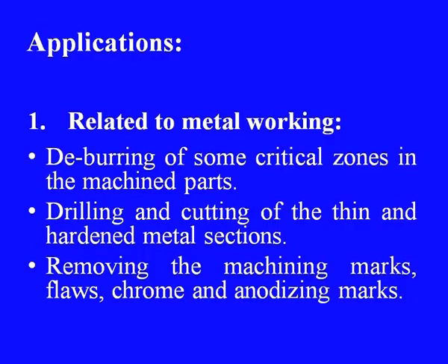Now, let us look at the probable applications of this particular process. These applications we can group under a few headings, like those related to metal working. So, this process can be used for deburring of some critical zones in machined parts, then drilling and cutting of thin and hardened metal sections, because this is essentially a process for hard and brittle materials, removing the machining marks, flaws, chrome and anodized marks, etc.